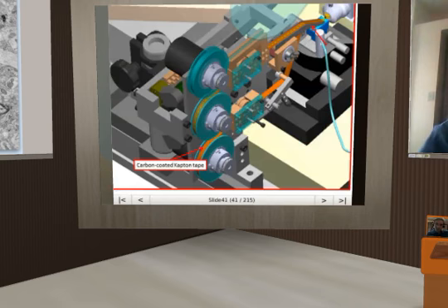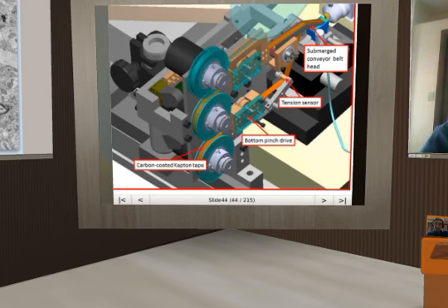It starts with a reel of carbon-coated Kapton film, about 8 millimeters wide, 50 microns thick. That is sent through a bottom pinch drive around a tensioner mechanism, and crucially, it goes around a submerged conveyor belt head that is submerged in the water of the diamond knife of the ultramicrotome. Sections are collected on this conveyor belt, which is drawn up with a top pinch drive and then finally collected on a take-up reel.